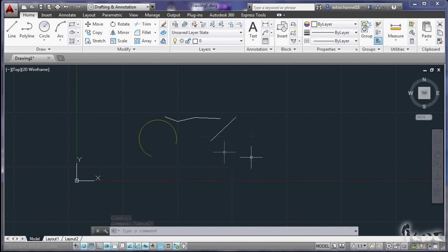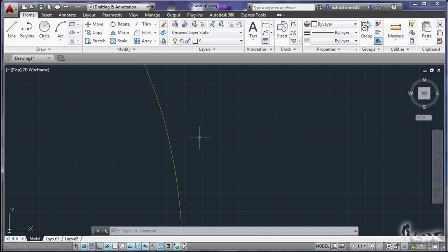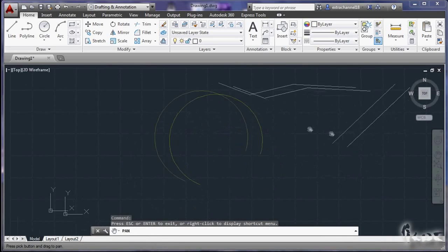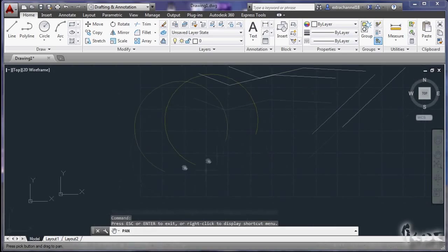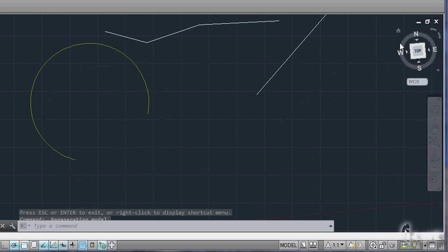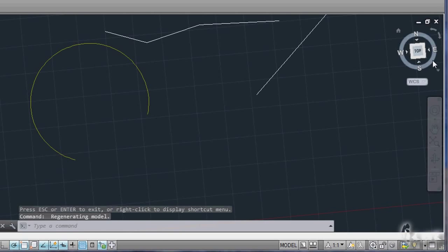Zoom is set simply through your mouse wheel. Use the pen button on the right to move through your workspace to check it better. To check your project, you can use the 3D map on the right. Until you go with 3D projects, the cube will show only the top face, meaning that you are watching the project from up to down. Click and drag the circle with cardinal directions to rotate your whole workspace.